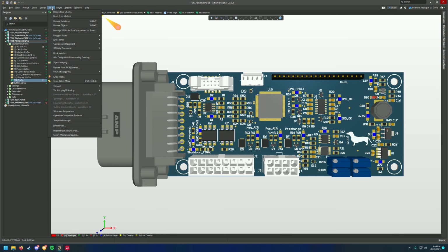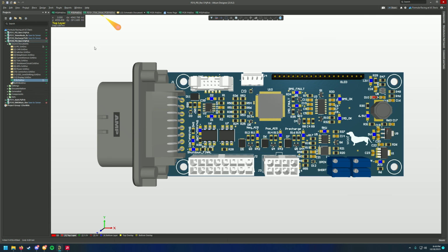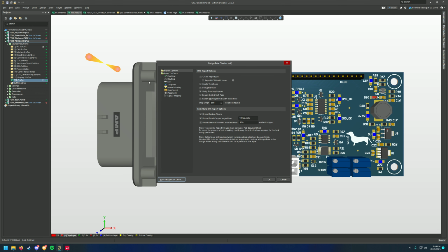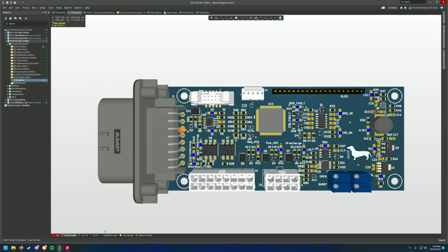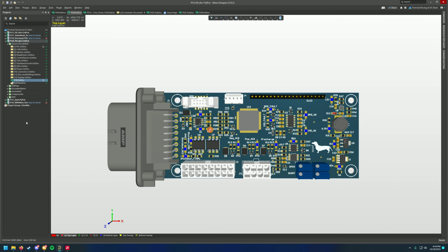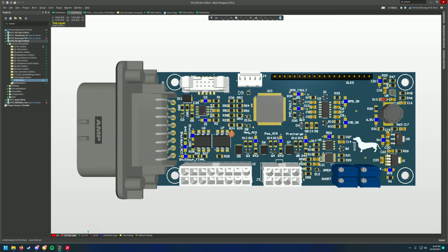So within the tools, you can see that for this one, we probably can't see, but the first thing here is design rule check, and the D is underlined. So if I press TD, then it's going to take me to the design rule check. So very useful, and that will help speed you up a lot. So don't forget keyboard shortcuts.